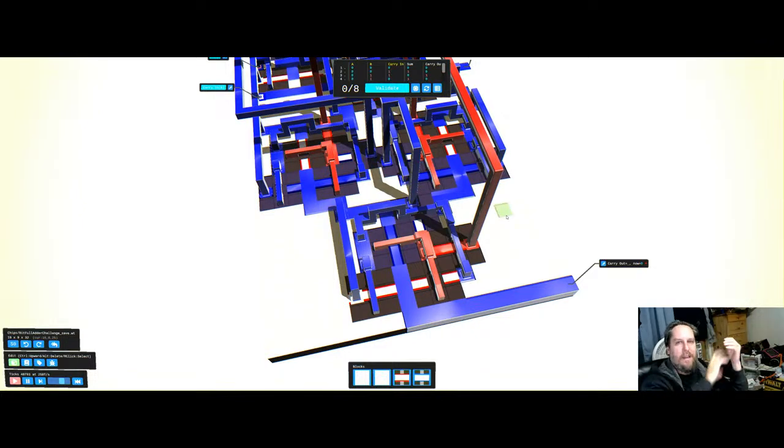You're probably having to do a splice sooner than you really would want to, because sometimes it's just the way it is. So I would say it's pretty average to have roughly a splice can for the fiber every most likely 8,000 feet. And again, there's certain instances where there's several within the 8,000 feet, or you can probably pull off maybe you have a long stretch through some woods or something, or maybe along a highway that doesn't have a lot of offshoots. Then maybe you are pulling that fiber quite a ways before you splice it.